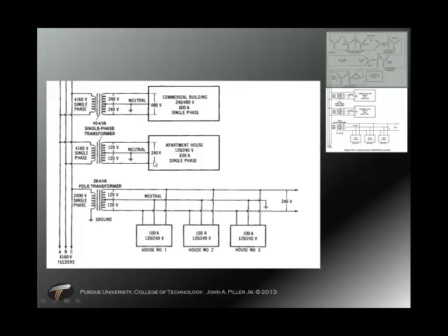We have 120, 240 set up. 480, 240 up here. 480 would be needed for HVAC equipment. We could go to a farm like this. There's a lot of equipment on farms that need 480. Go ahead and go to lighting, whatnot. Inside this building, we would have a 240 to 120 or a 480 to 120 to distribute to low voltage.